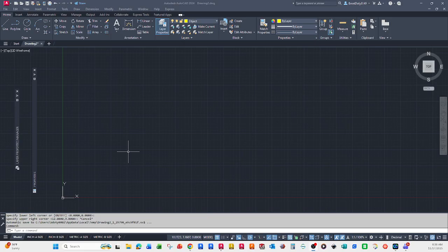That limits how much you can have in memory at one time, and so that limits how much space you can use in here. So that being what it is, limits are important because if you go too far outside of the limits, you won't be able to draw. So if you ever run into something where you can't draw and you can draw in some other part of the screen, then you've probably gone outside the limits.